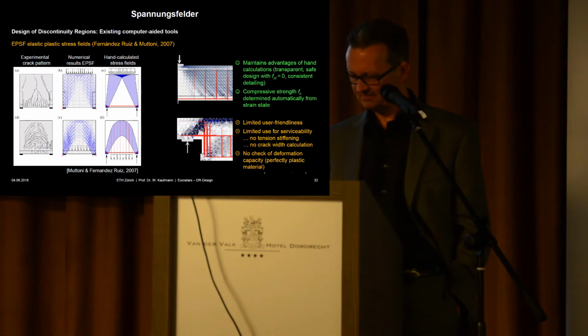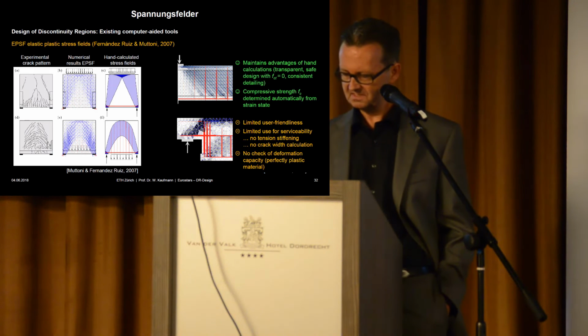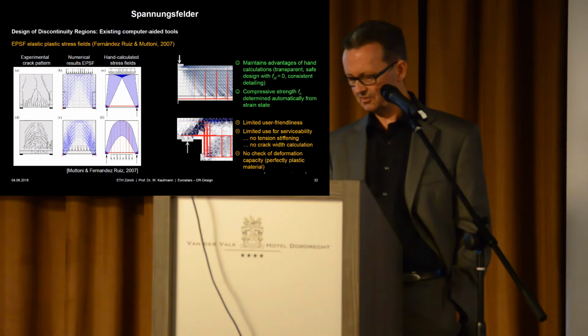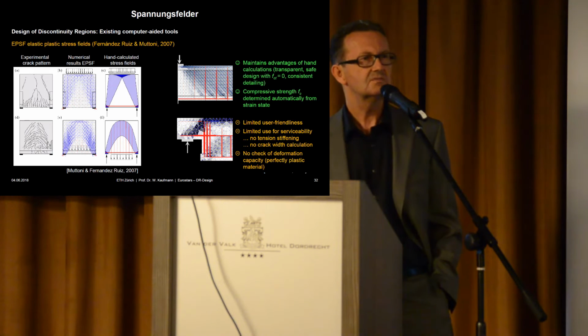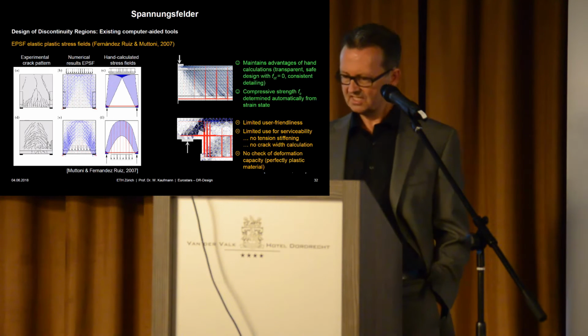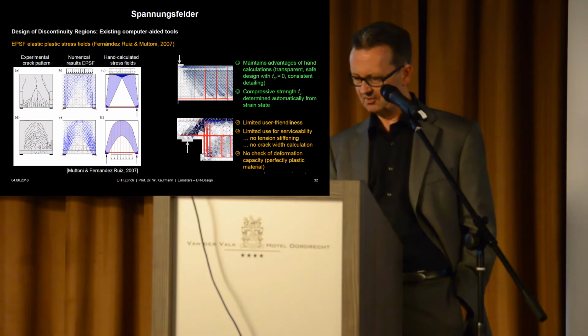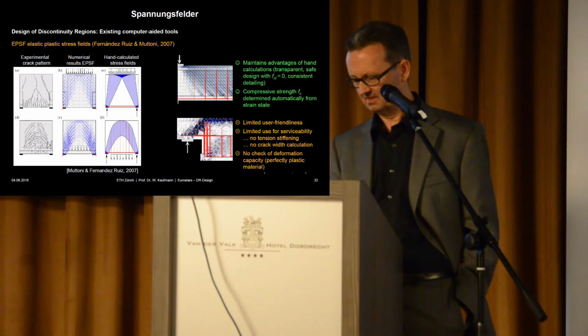Now, it's not only advantages though, this program. What's really good, it maintains the advantages of hand calculations, because they really use for concrete and reinforcement linear elastic, ideally elastic material. So for both the concrete and the reinforcement, with a slight hardening to make it numerically stable. But they use this, and for the concrete, of course, like this. So no tensile strength.